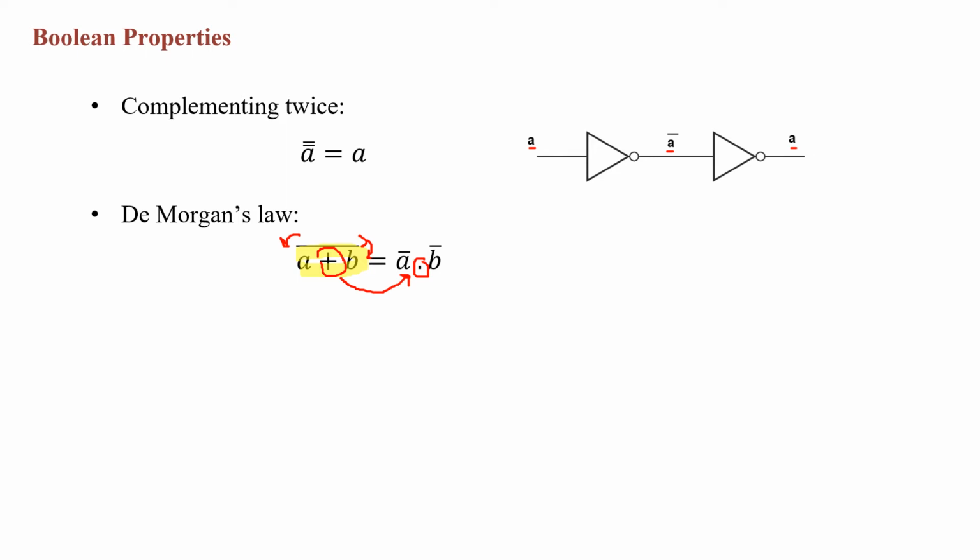the OR into AND. So this is useful if we want to get rid of the plus sign in any expression without changing the expression. We can simply complement twice by using the first rule and then distribute only one of the complements, which will take care of the conversion of the ORing into ANDing.